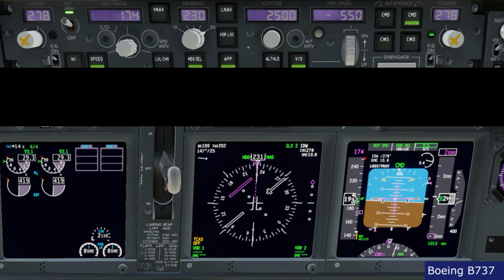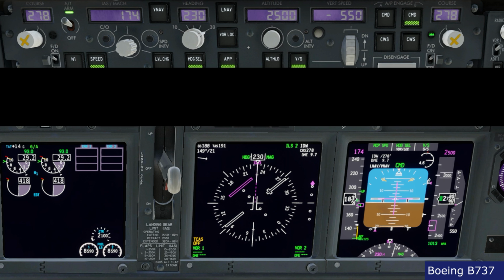The aircraft starts descending at the selected vertical speed because we are below the glide slope, so our intention is to intercept the glide slope. If the glide slope becomes captured, then the glide slope will become green, and we say it on the 737, the only function that does not have altitude armed is the glide slope. So if glide slope goes green, the altitude does not arm underneath. If otherwise we have a different vertical mode, the altitude always remains armed.